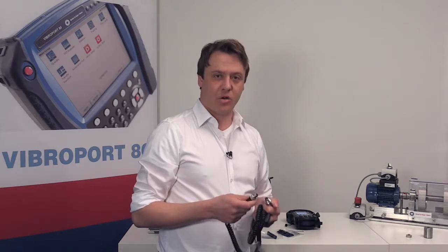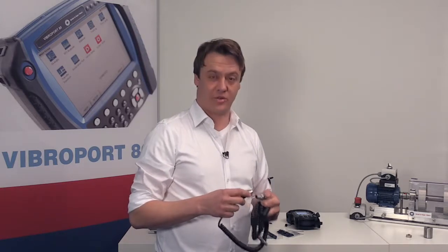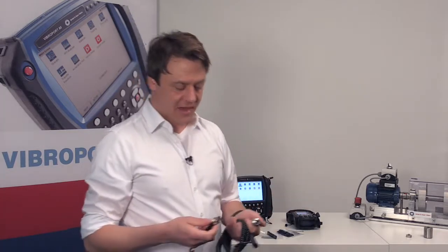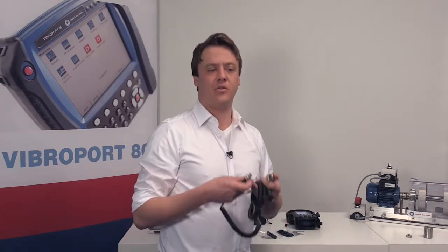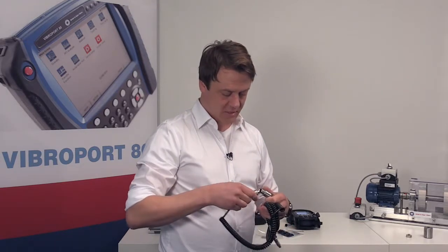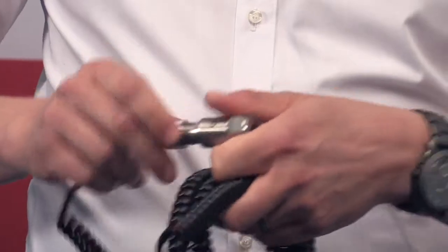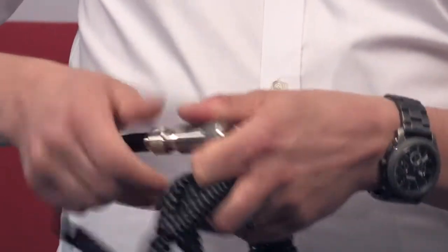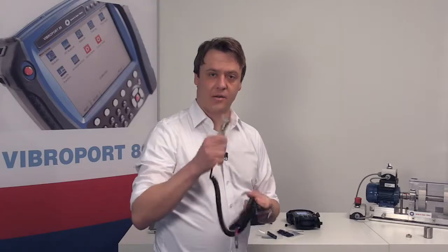And why do we have screw-type connectors? They are very, very robust, and they fix together the measuring chain. Suppose in the measuring chain something is loose, then it can start to rattle and can introduce false vibration signals, which you don't want to measure. So let's look at how to screw this together. And if I screw it together, it is very easy and very hard, and nothing is rattling.